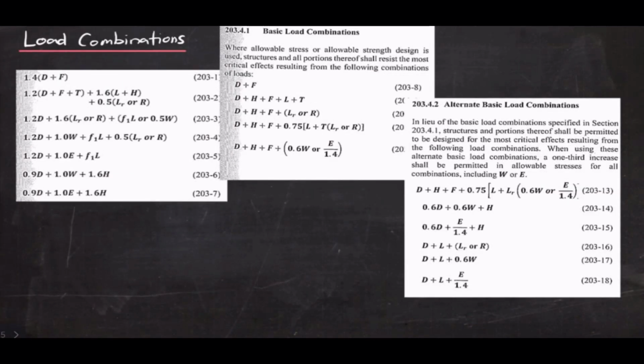Let's review certain things about the load combinations. What are the load combinations that we use when we design or analyze a footing? So these are snippets from our structural code. The first one, these are the ultimate load combinations, and we use them when we design the concrete. We will be using this to check the shear in concrete.